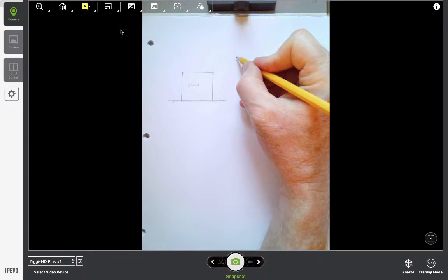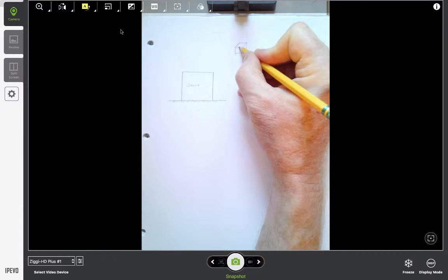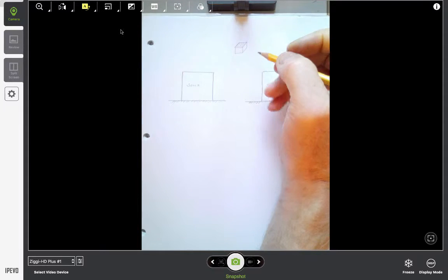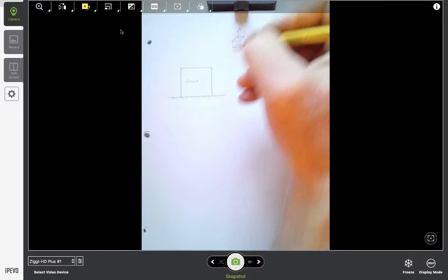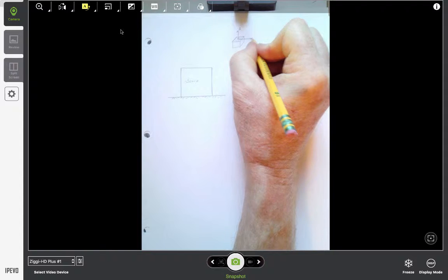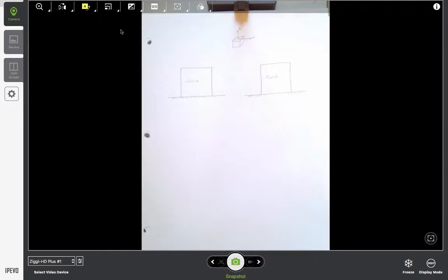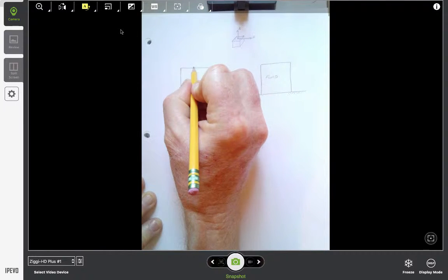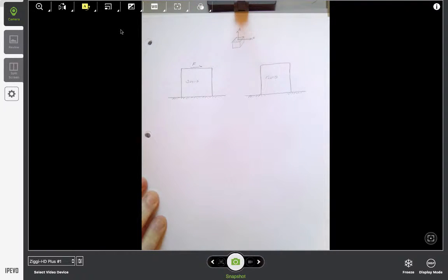And if we look at either block, we're going to apply force to the top face. There's a vector that represents the area, the shaded area, and we're going to apply a force tangential to that plane that's pointing outward. So on the solid, if we apply that force, a solid's pretty easy to imagine. Put a little bit of JB Weld on a plate, glue the plate to the top of the solid, glue the bottom of the solid to the plane, and then pull on it.